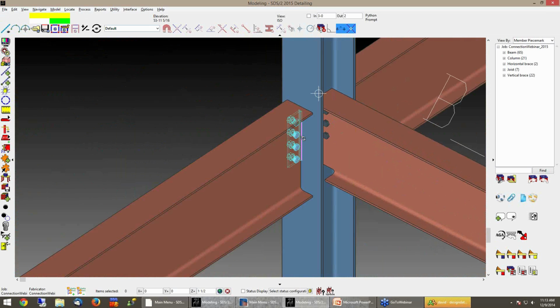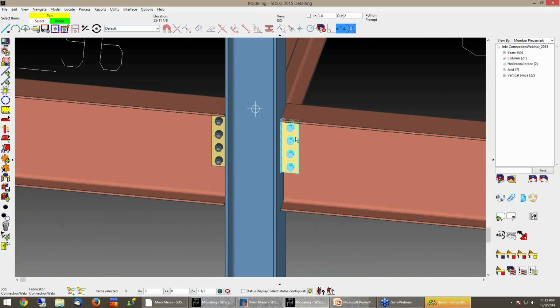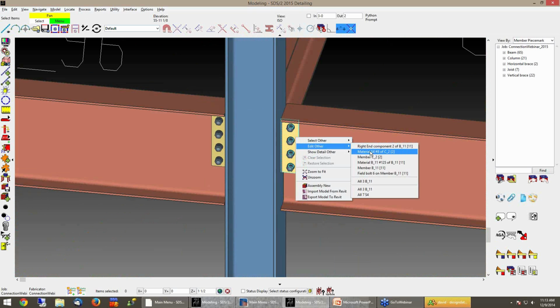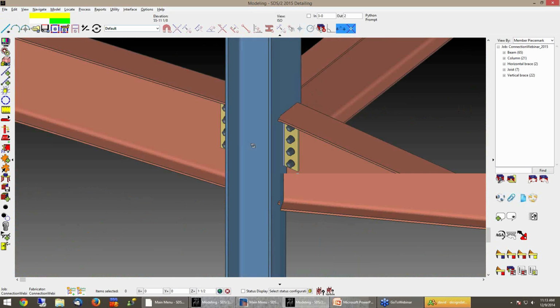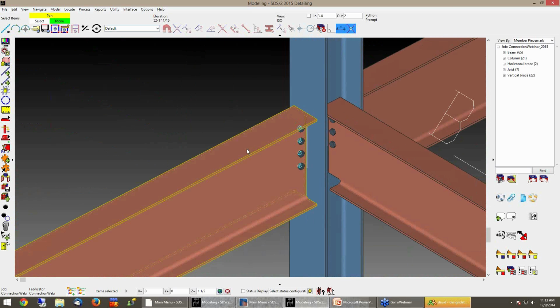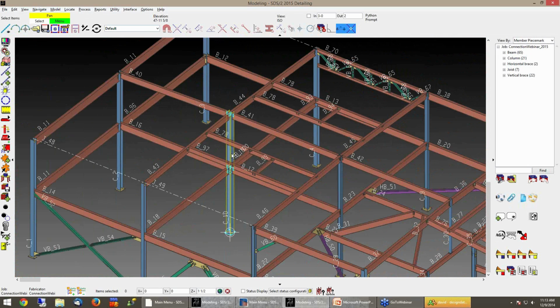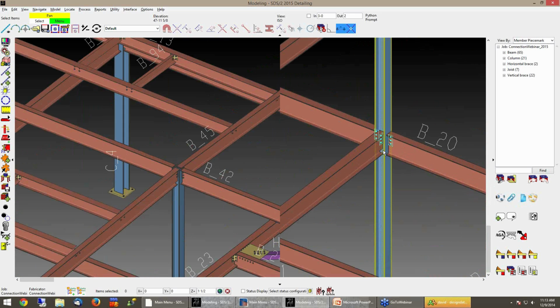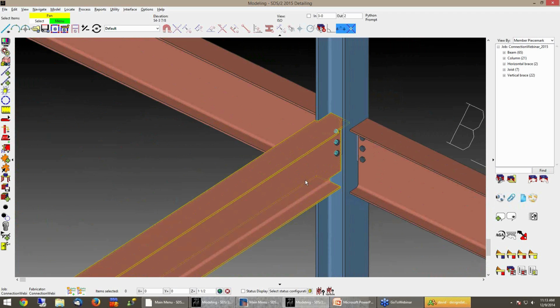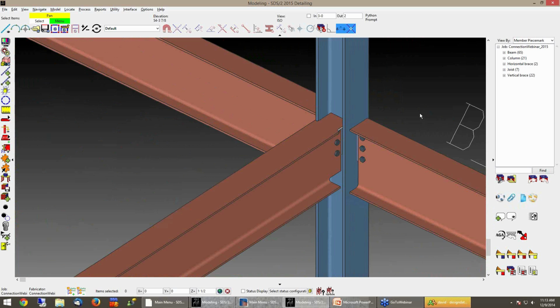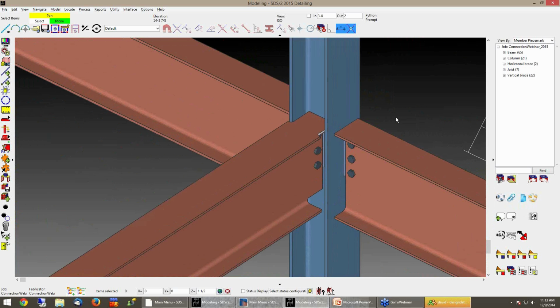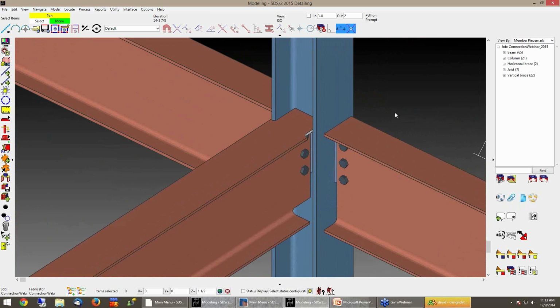Let's go to a little larger beam here and show you. Same thing. Got that standard piece mark. In this case it's an S4 because I just set it up based on the rows of bolts. But it is redesigning using that user-defined connection for us. The other thing about user-defined connections now in 2015 is that if we save that through the connection component window or the member edit window, the end preps are going to get saved with that as well.